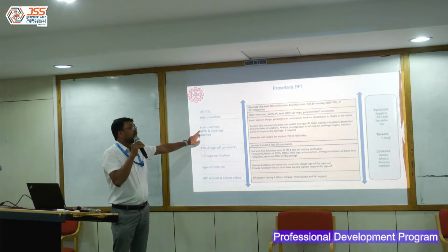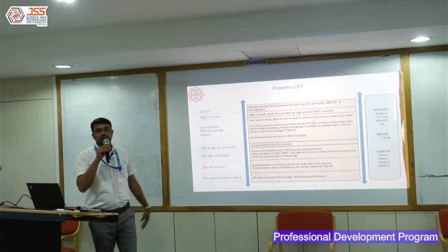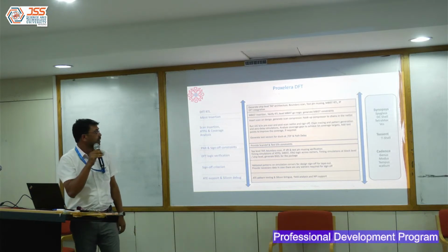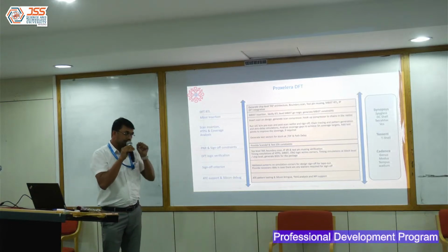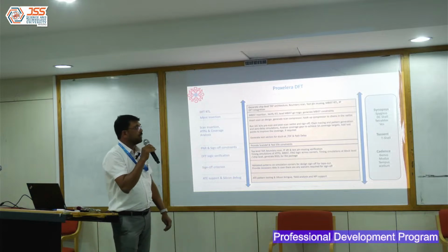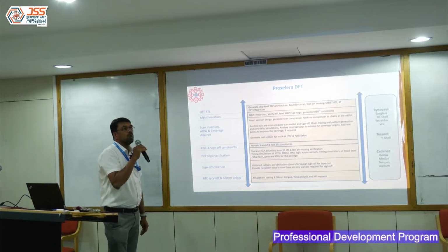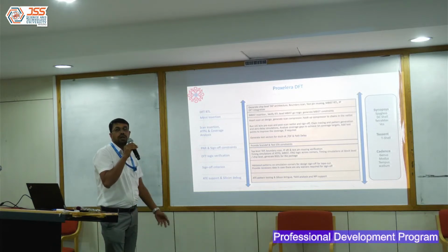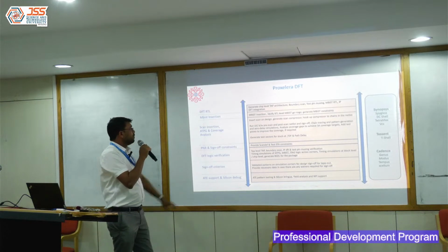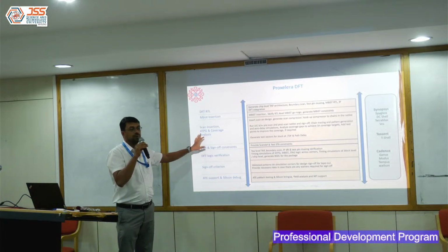Okay. Once you have the scan insertion done, you have to go through a process known as ATPG, Automatic Test Pattern Generation. There is a tool named Tessent, and this Tessent tool will help us do the ATPG. And we also do a simulation.